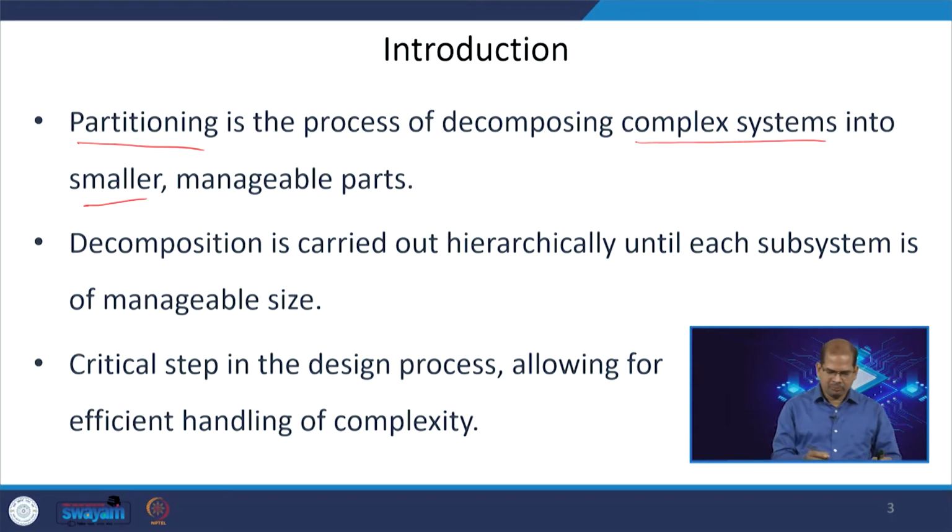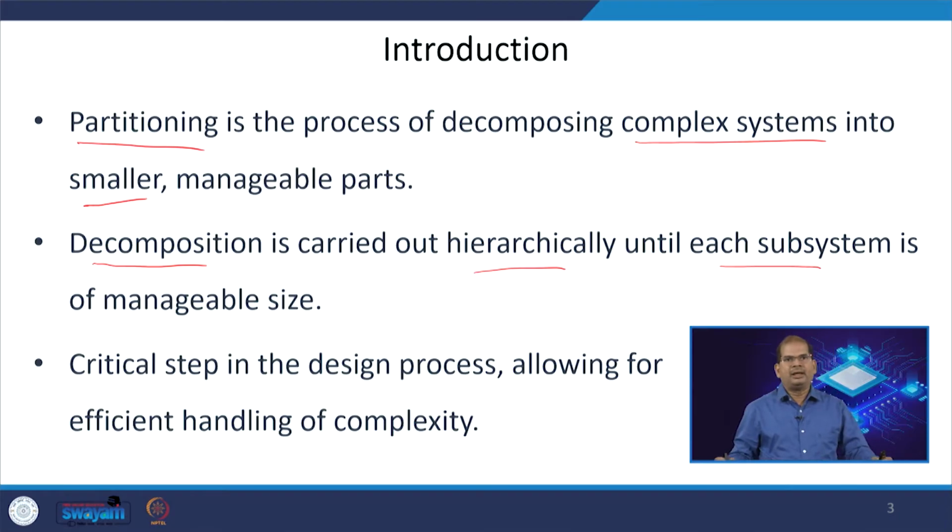The process of decomposition is done using a hierarchical approach, such that each subsystem can be implemented in a smaller area. Let us say for chip level partitioning, I have a bigger chip and I want to design a processor. Inside a processor I have a control unit, ALU, and pipelining stages. I need to divide each one of them in such a way that I can design them independently and combine them at the top level, which can be done in parallel.